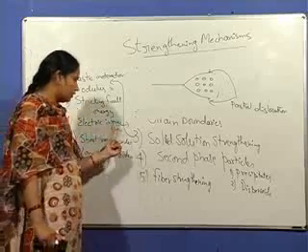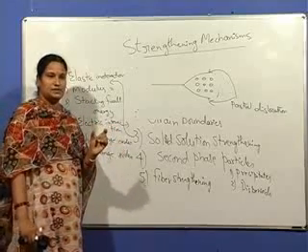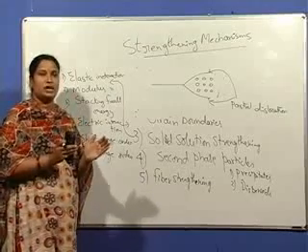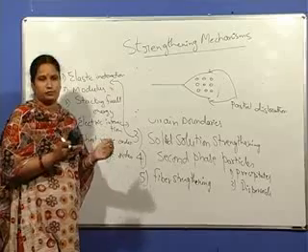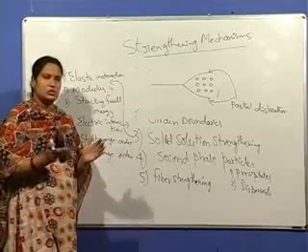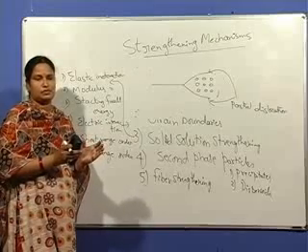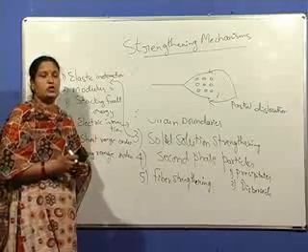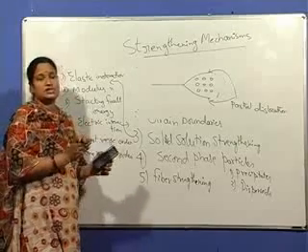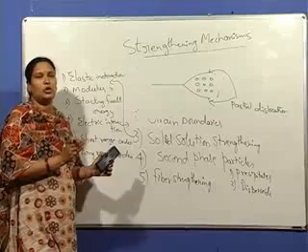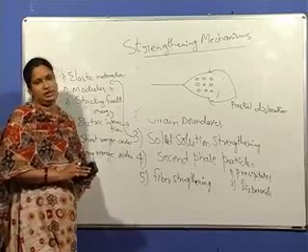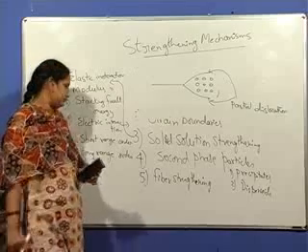In the case of short range order, the solute atoms group together in such a way that they have more dissimilar neighbors. And clustering is also grouping of the solute atoms over small areas. So for a dislocation to move, it disturbs or alters the local ordering, thereby it requires more energy to bypass it.